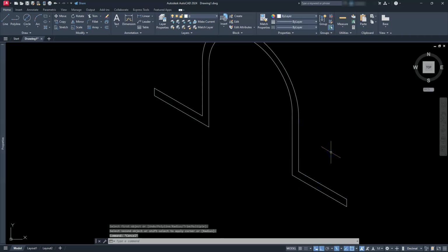All right. The reason why I can't put a radius on those fillets is because remember that this is an isometric. So the traditional fillet command will not work. So if you did use the traditional fillet command, it's going to look a little kind of goofy or kind of lopsided. All right, the way that we're going to create these fillets using isometric circles is that I got to kind of create that shape if this is going to make sense to you.